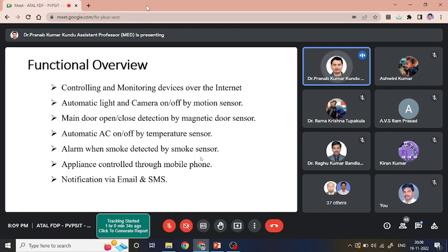Alarm when your tank has been filled. You have started your pump to fill up the water, or you can also make the pump start automatically. How? There may be two types of sensors. Correct? While the tank is being filled, the pump will stop automatically, and when the level of the water in the tank lowers down to a prefixed level, the pump may automatically start.